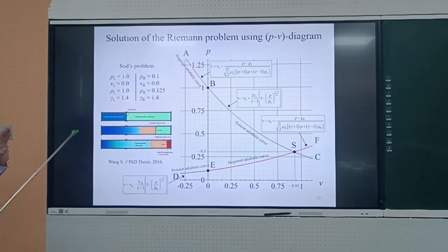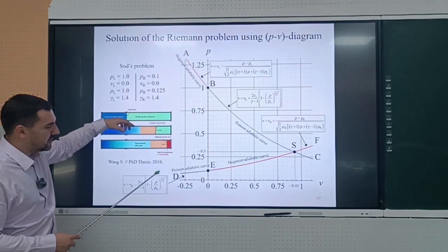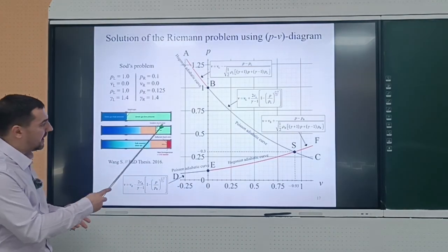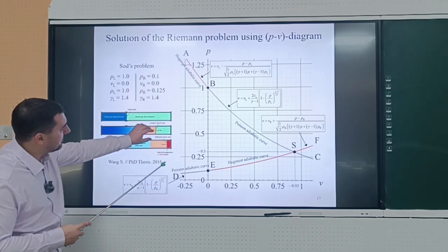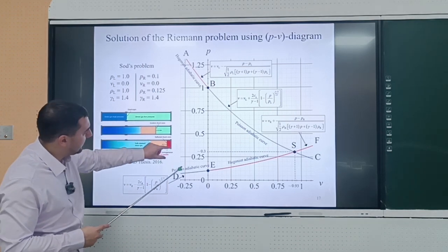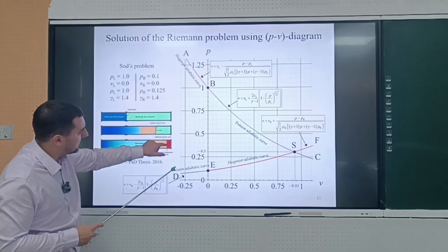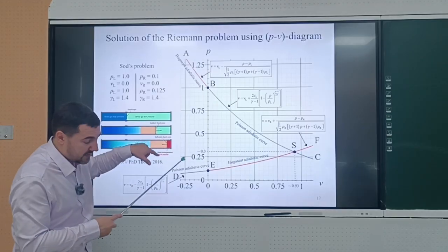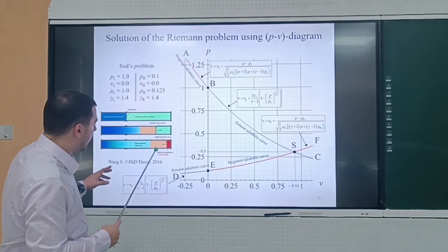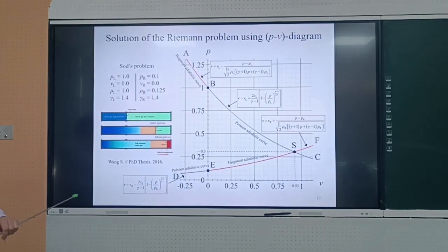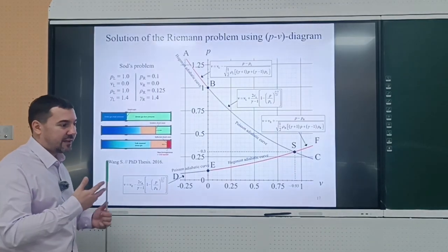Also, you should understand that I explained to you just the one-dimensional behavior of this media. In reality, in a shock tube, it's a 2D or actually 3D problem; boundary layers will develop behind the shock wave, and after the shock wave reflects from this end wall, it will interact with these boundary layers and so on. So that's to the question of the errors of the mathematical model.